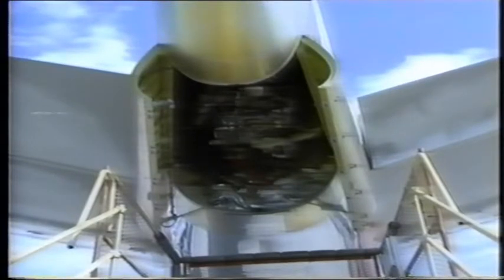The APU is a small gas turbine that provides pneumatic and electrical power to the airplane during ground operations. Remember, before applying power to the airplane, consult the Boeing maintenance manual and go through the safety checklist. Control for the APU is provided by the APU controller, and system indication is shown on the ICAS maintenance page.